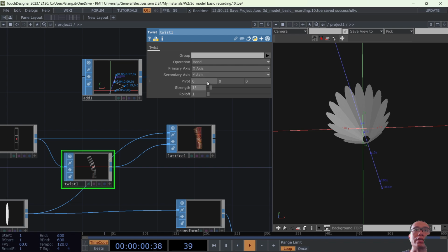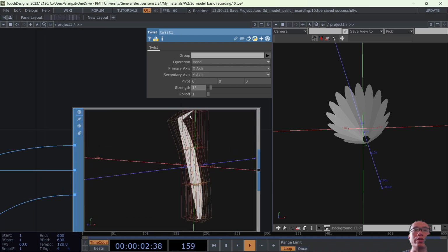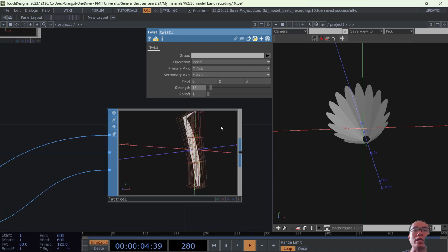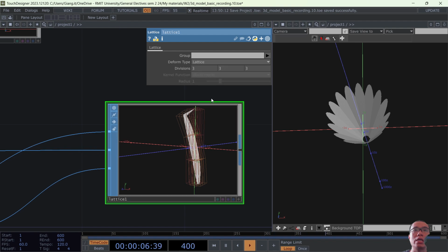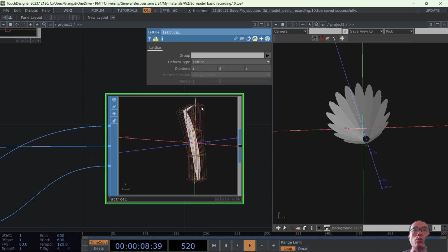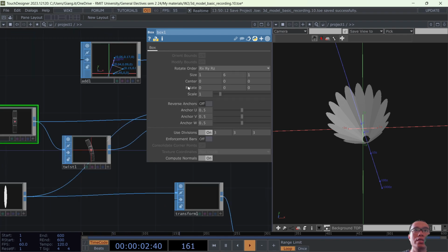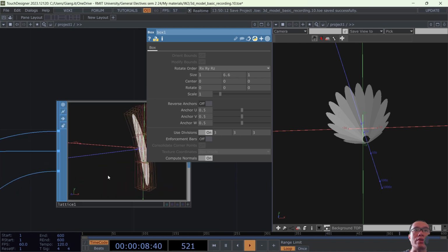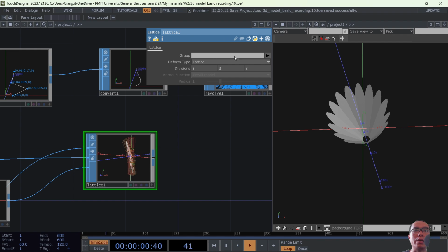And on the secondary axis over here, when I bend it, you're going to see that it's actually causing this geometry to be deformed, but on the top over here it's deforming very weirdly because this bounding box doesn't cover the whole geometries. So I'm going to increase the size over here a little bit to fix that. Okay, so now everything should be deforming as I like.